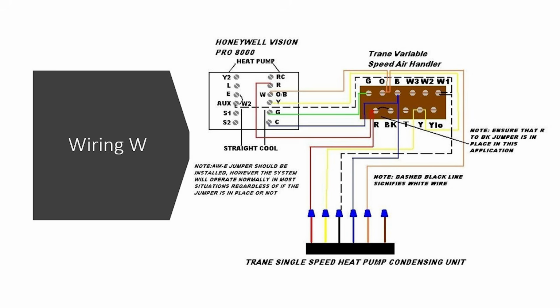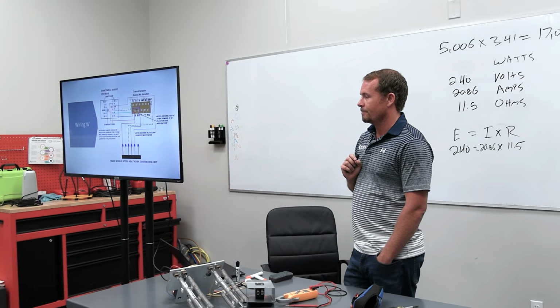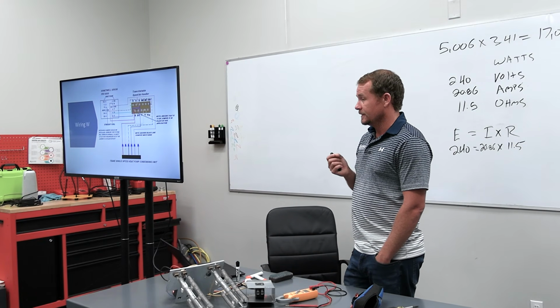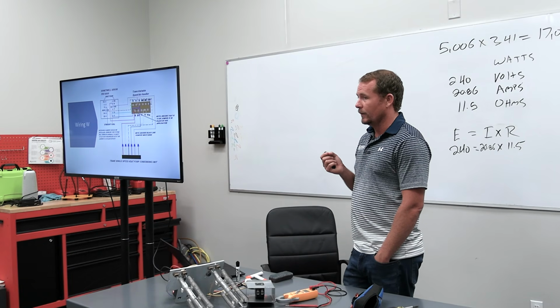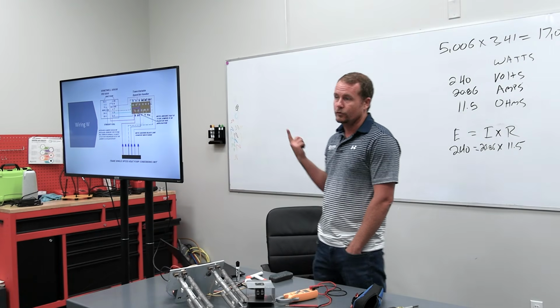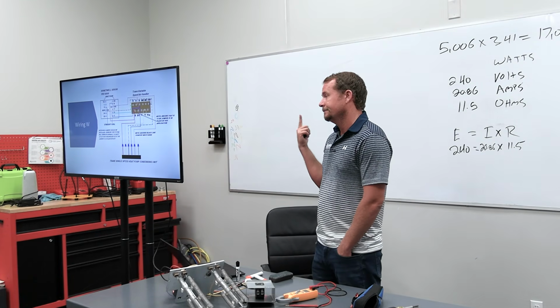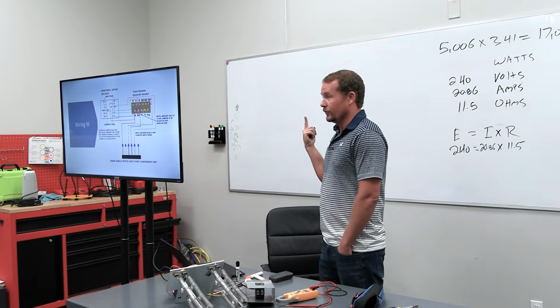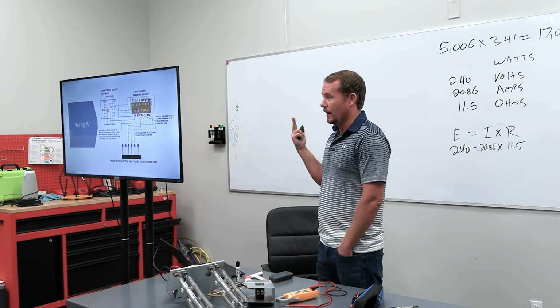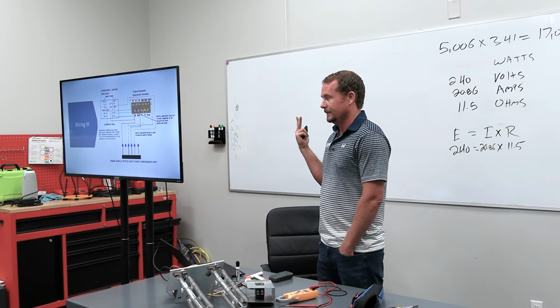Why would we do that on some older thermostats? Why do you think? Is it a heat pump function? Because if it's a heat pump, Y1 and W1 are the same, right? What does a heat pump do when you need to run first stage heat? Calls Y. It calls Y with no reversing valve. What does it do when it runs first stage cooling? It calls Y with a reversing valve, right?